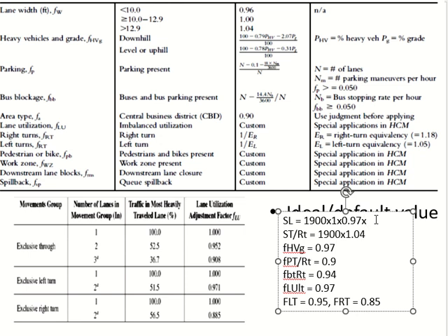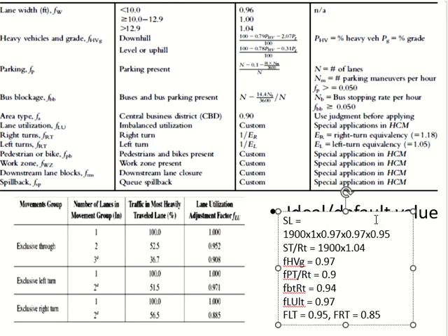Left turning utilization factor, it was 0.97. And then we have the left turning factor, which is 0.95. For the right turning and through, we will have the 1.04 is for the lane width. Then we have heavy vehicle and gradient, which will remain as it is. Then we have one for parking.